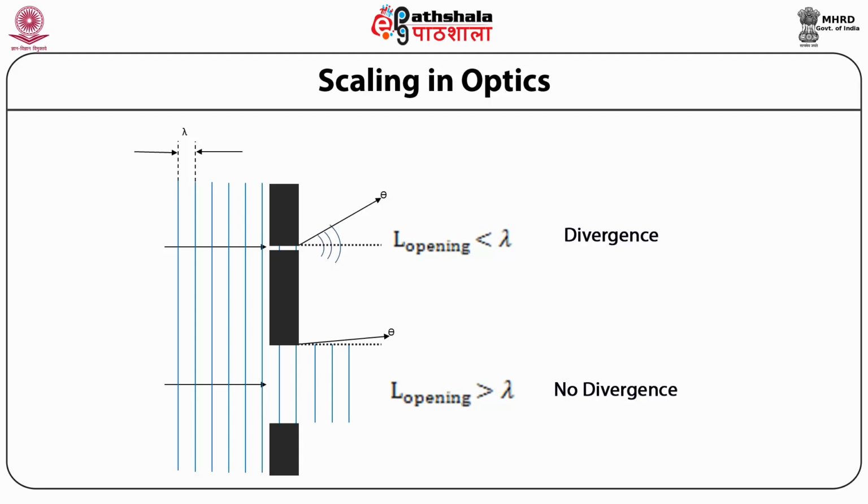In micro-nano electronics, small devices can only be fabricated using photolithographic or E-beam lithographic techniques, in which photosensitive materials are selectively etched using light or electron beam.